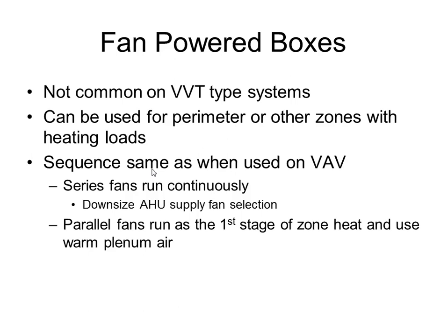Fan powered boxes are generally seen with VAV type systems. However, for VVT, you can use fan powered systems. You don't really see them because VVT systems are a lot smaller, but the application is exactly the same for VAV systems as VVT. You can use them, for instance, if it's a series fan powered, if you need that extra push down the ductwork in order to overcome that extra static pressure. Works the same.